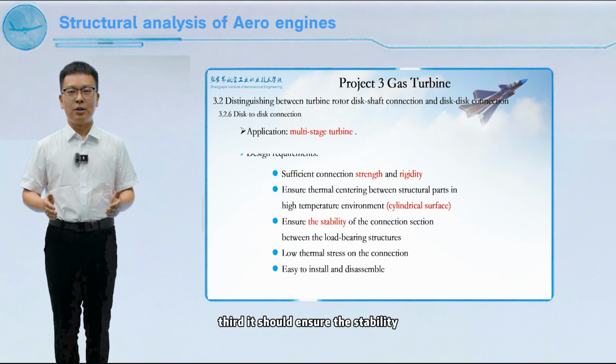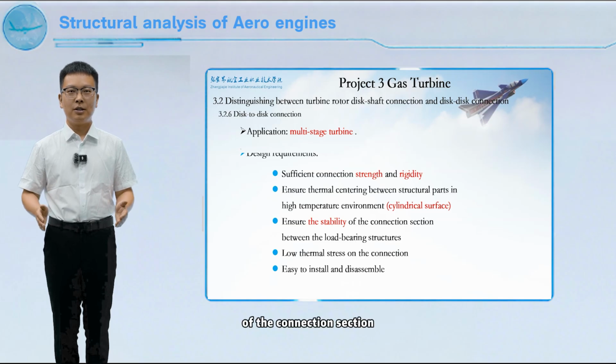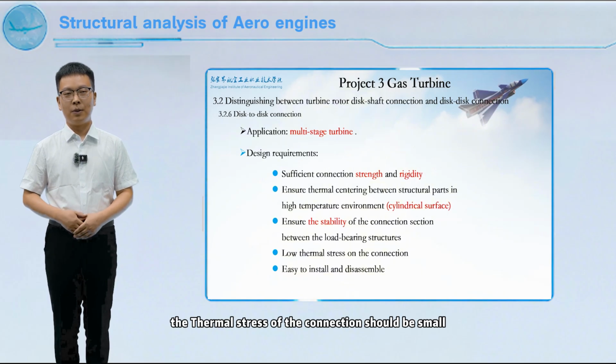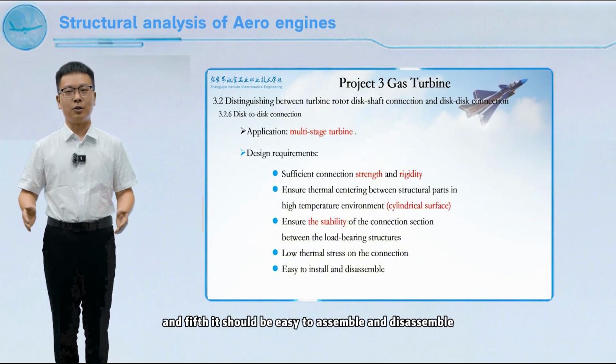Second, it should ensure thermal centering between structural parts in a high-temperature environment. Third, it should ensure the stability of the connection section between the load-bearing structures. Fourth, the thermal stress of the connection should be small. And fifth, it should be easy to assemble and disassemble.